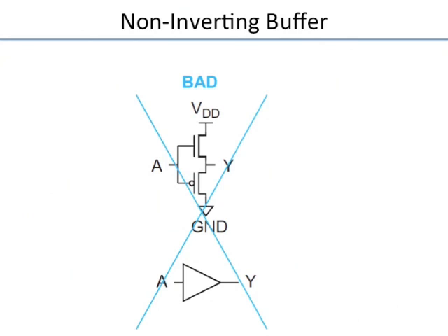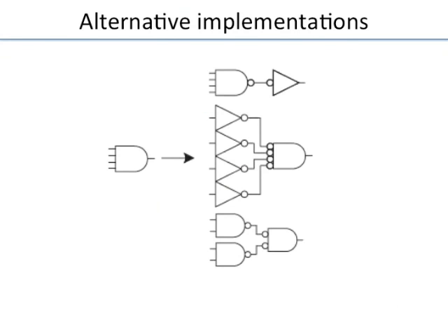So now if there is a particular logic function, we saw AND or invert or NAND2, NAND4 and so on, there can be multiple ways of realizing that. For example, let us take the NAND4 gate. That means it's a 4 input NAND gate. So one approach is what? Say here, for example, it's a 4 input AND function. I can do it this way. I can have a NAND with an inverter.